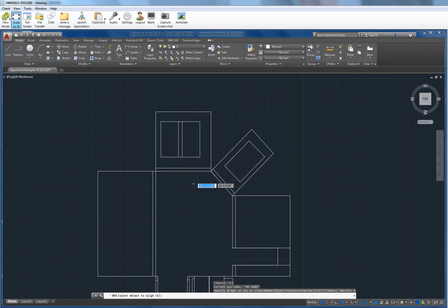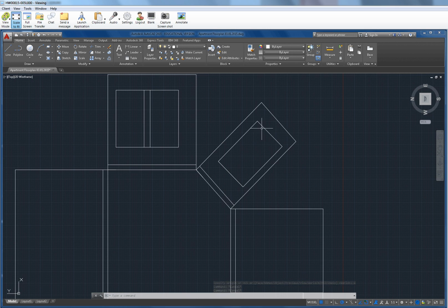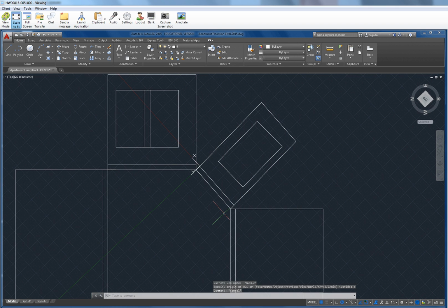UCSE aligns the UCS to a pre-existing line, which we can see there's a problem with the drawing, but it's all right. Like in plan, that's why UCSE is important for these odd angles, so we go always perpendicular, right? So this is skewed right now, right? Like it's off angle. Okay. What do I do next?